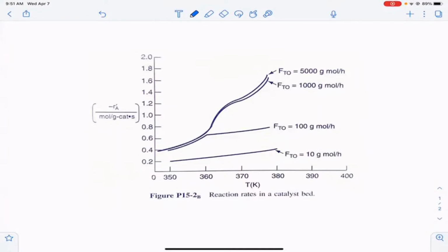In all the math that we've done so far this semester, hopefully it comes out that as you're changing the temperature, you might influence the kinetics and the internal mass transport. But by saying that you influence internal mass transport means you're going to change the internal effectiveness factor. So what you need to be able to do is use the data set to find the effectiveness factors at a given operating point.